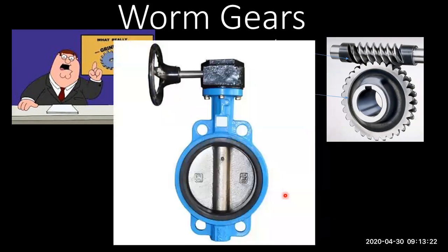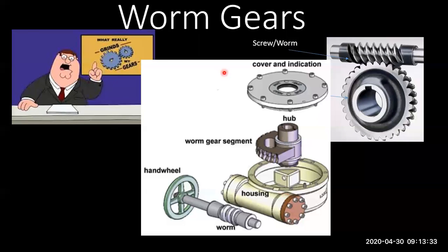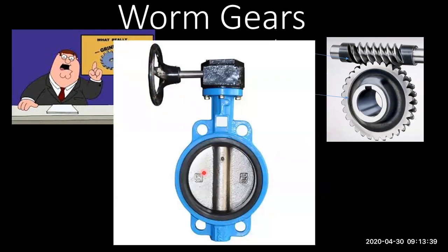And this is one other manually operated mechanism where you can turn this worm wheel inside the mechanism. It's similar to the previous one, with a worm and a worm segment, and this is a gate valve which opens gradually. Slowly it opens up, and you can control the flow of fluid.